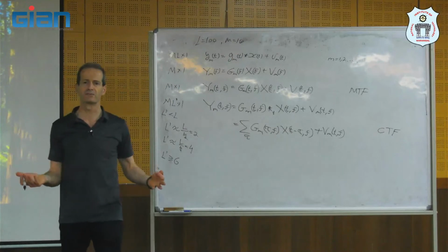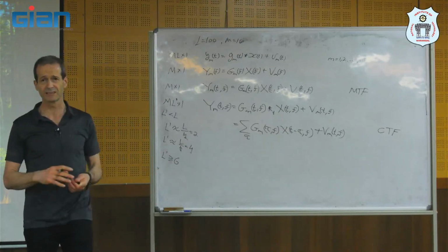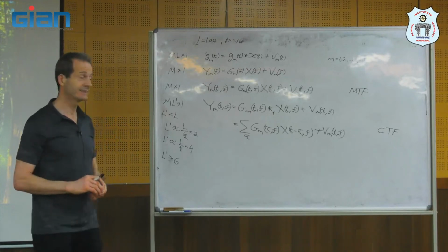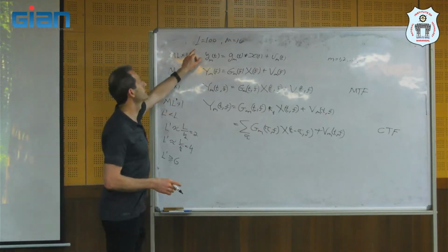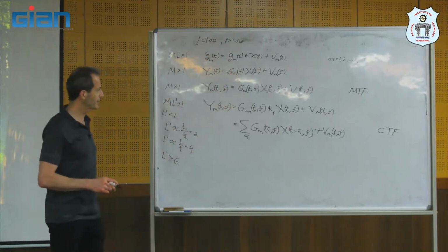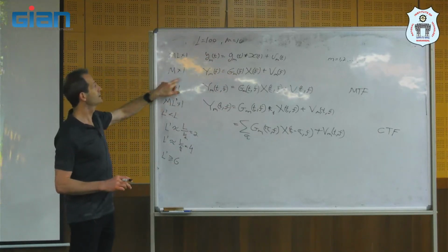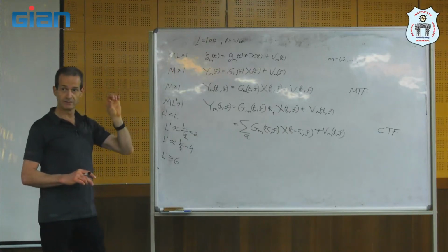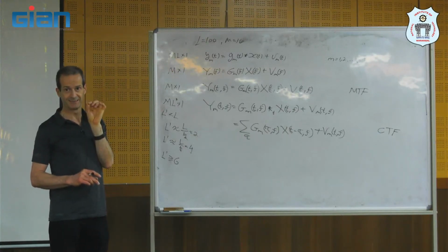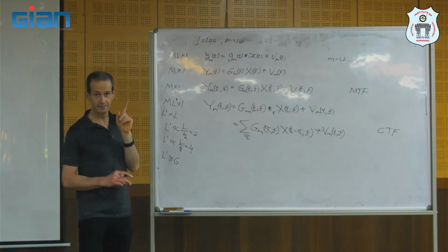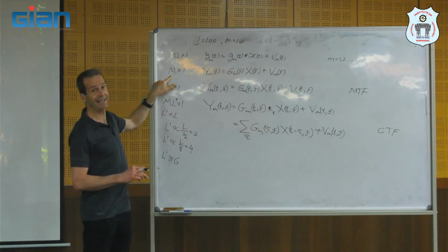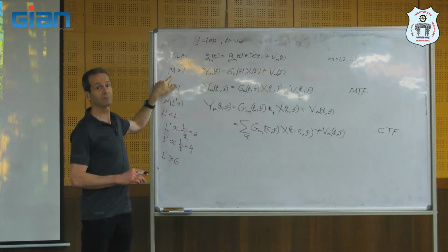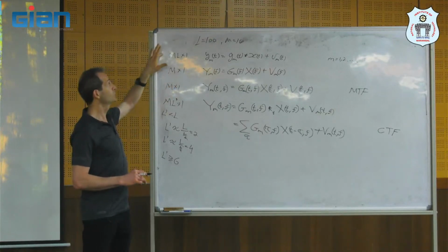So we work with correlation matrices 1,000 by 1,000, which is large. And it can be even larger if L increases. So here, we solve 100 smaller problems. We find 100 filters of length 10, and we work with correlation matrices of size 10 by 10. It's a huge advantage.